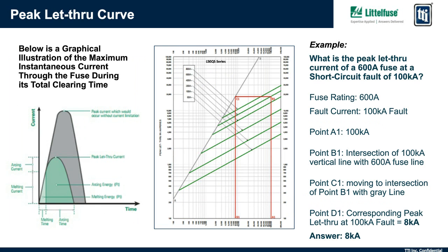Yes, that is exactly what it means. So again, if you have a 100 kA available fault current, having a fuse in the circuit could reduce that 100 kA fault current, depending on the fuse rating, anywhere from a few thousand amps up to 30 or 40,000 amps. The higher the rating of the fuse, the more let-through current we'll have. But yes, that's absolutely what it means. The actual let-through current level will be less than the potential or the available fault current level.